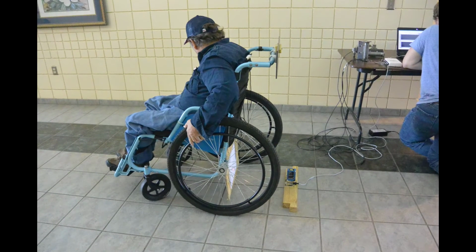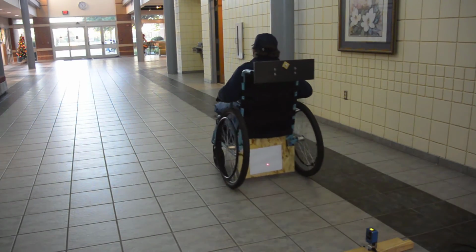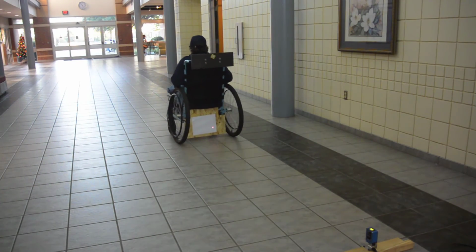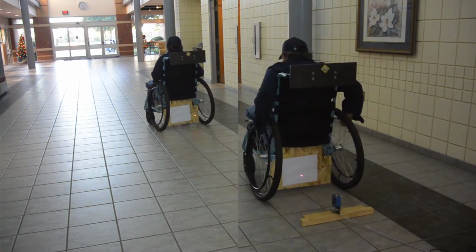While the load cells are useful for demonstrating a force impulse, as we saw, we really don't need them to quantify rolling resistance of a wheelchair. Now we will ask Will to give a single forward stroke to get the wheelchair going. After the stroke, rolling resistance will be a force acting on the wheels to slow down the wheelchair. By measuring time and the change in velocity, we can determine the average rolling resistance force.